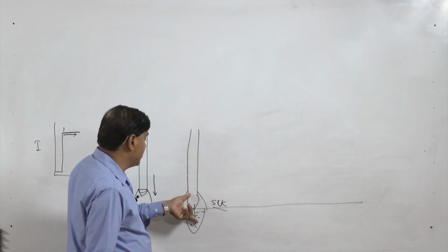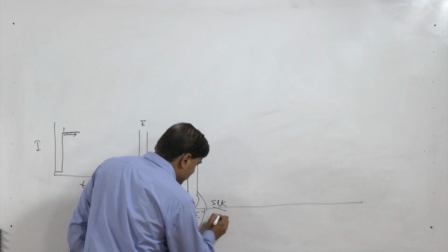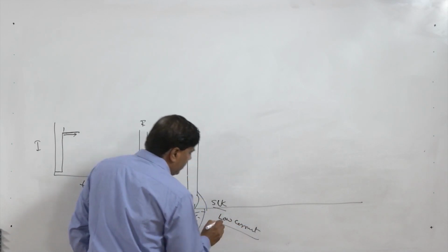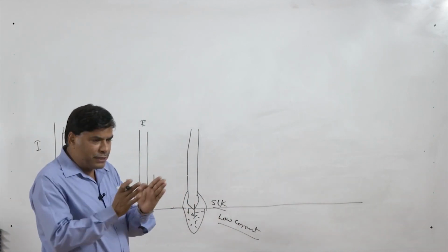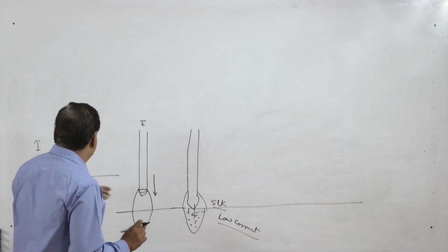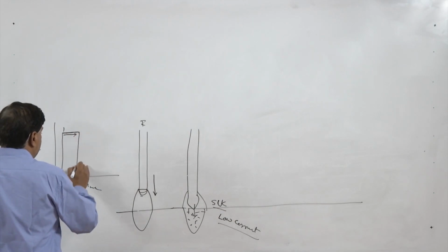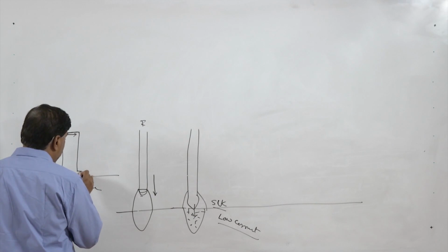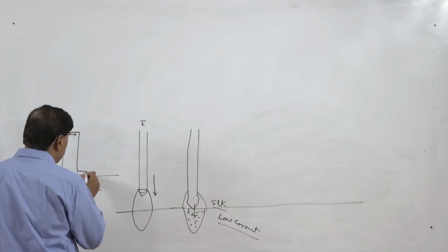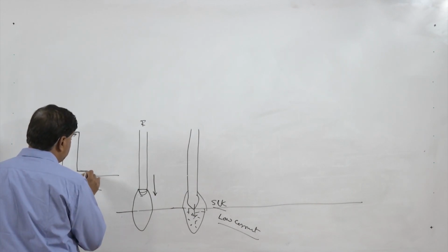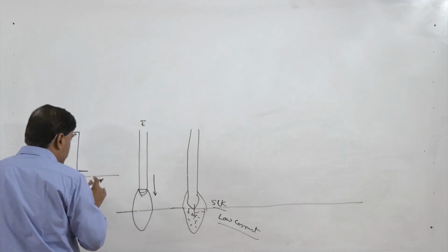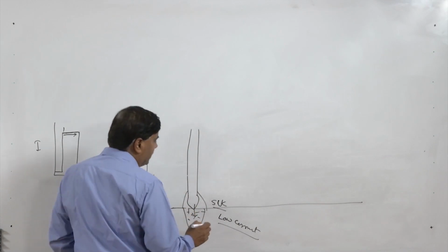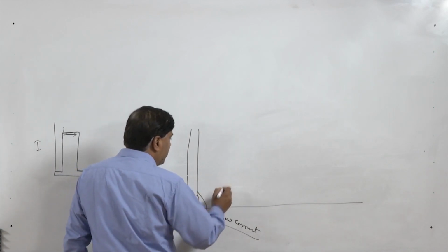So short circuiting takes place, but at this stage very low current is ensured. So the transfer is very smooth because current magnitude is reduced. At this stage of short circuiting, current is lowered. Once the drop is transferred, after touching, this electrode is retracted.